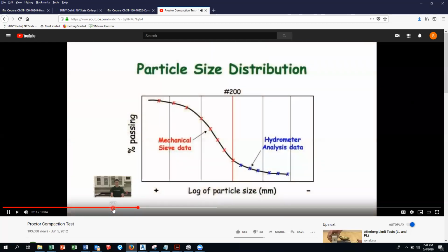The Proctor compaction test consists of mixing soil with water to a predetermined moisture content. This soil-water mixture is then compacted into a mold of a specific volume with a standardized energy. At low moisture contents, interparticle friction will hinder compaction, resulting in a low unit weight. As moisture increases, the friction between the particles reduces, and the particles will compact into a more dense pattern. Past a certain moisture content, known as the optimum moisture content, water will start to take the place of dry soil particles, and the dry unit weight will again go down. By conducting several standard Proctor tests at varying moisture contents.